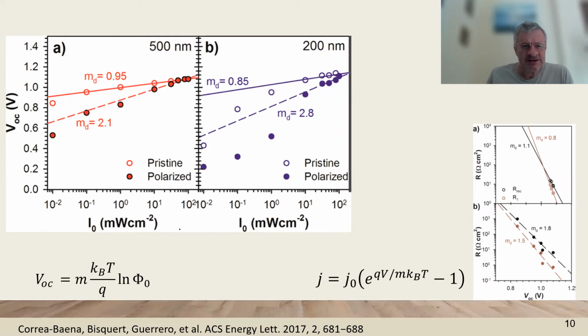So here is an early example of the determination in a perovskite solar cell. We can see that in the first case here, it's nearly 1 because this is for a pristine solar cell that has not been yet polarized. After going through polarization and JV curve measurement, this diode quality factor was changing to 2, indicating a strong modification because of the ionic effects, etc. So the measurement itself was modifying the perovskite solar cell, although this can later be recovered.